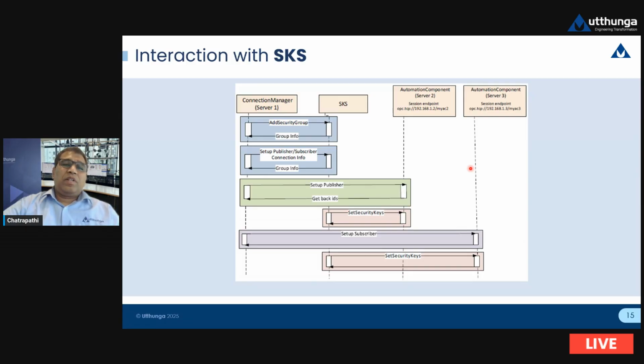But for today, we are only going to look at how the existing OPCUA security interactions are adapted for OPCUA FX so that the FX communication themselves become secure under the same security policies and the endpoint security that has been adopted for that specific OPCUA server implementation.